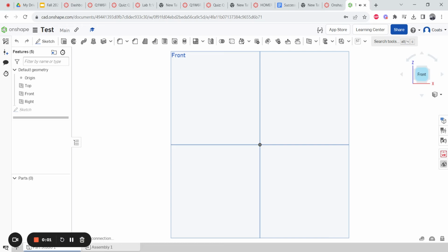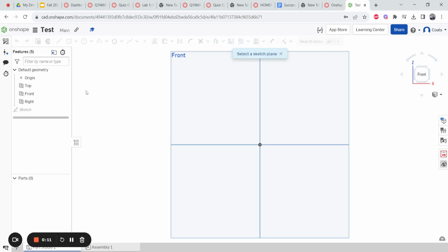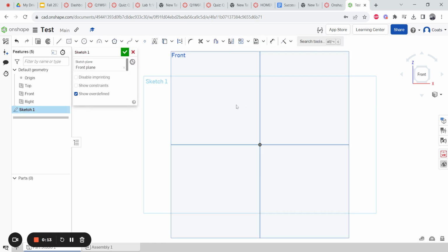Okay, this video right here is about making circles and the primary arcs you're going to be using in this class, especially at the very beginning of the school year. So again, you're going to sketch. You're going to tell it where you want to sketch. I'm sketching on the front plane. Easy one, center point circle.